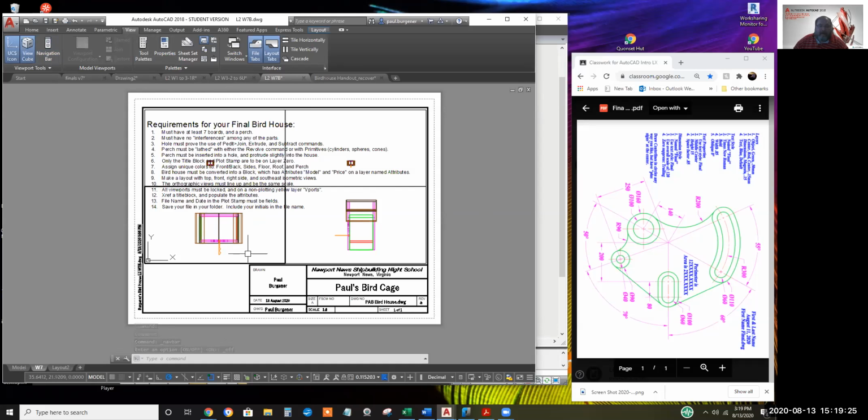You know, always something, ain't it? All right, I'll do it the manual way. UCS, enter. Let's see, I'm looking at the XY plane, so I want to create a UCS that's negative 90 degrees from the X axis. So click on X option, type negative 90, and nothing happened.